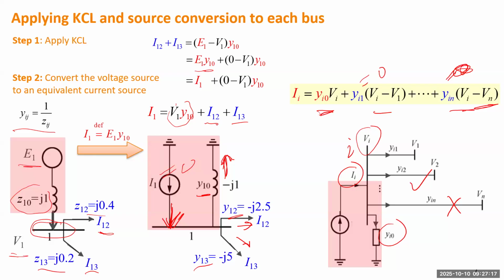But the convenience of using the Kirchhoff current law at each bus is you don't change the number of equations, because those substations are there. Unless you remove a substation in some planning study, or split it into two, you are going to change the number of equations. Even if you open a line, two lines, three lines, it doesn't change the number of equations. So that's why this standard model is very convenient for contingency analysis. Any question? All right, if that makes sense, let's move on.